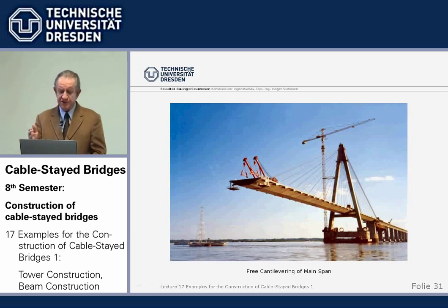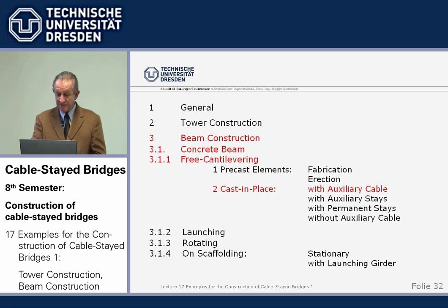All these bridges in Argentina, I think we did 5 of them, have in the range of 300 meters, 350 meter main span. Now, we've dealt with precast element. Advantage, the precast elements are built under controlled conditions, independent of weather and so on, and they can be done very precisely. And they have, say, 1 year or so of age when they are installed, so their shrinkage and creep capacity is greatly reduced against cast in place fresh concrete.